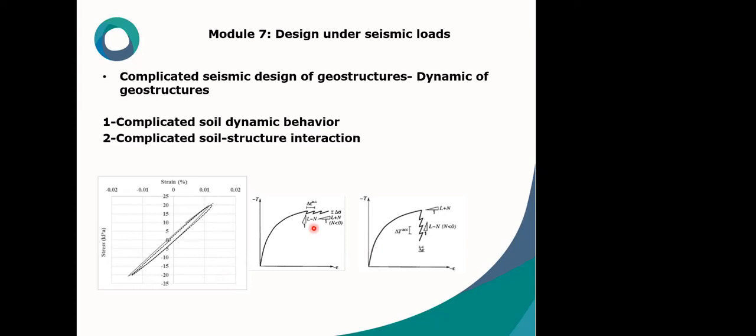The dynamic responses of above ground structures are evaluated by the inertial forces, which may be different from those of underground structures. On the other hand, underground structure displacement does not differ significantly from the surrounding soil. Thus, their seismic responses are controlled by the ground strain and ground displacement, due to the soil structure interactions.